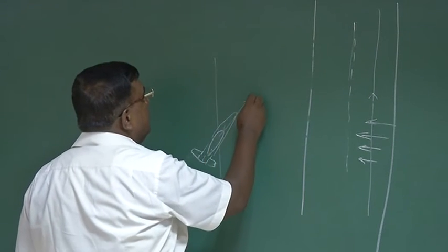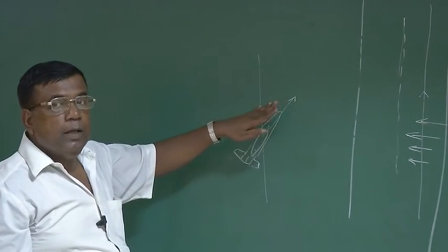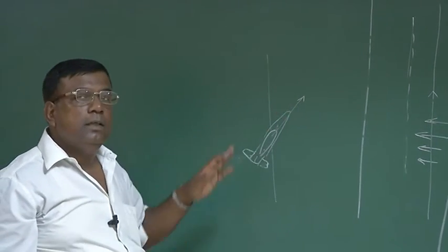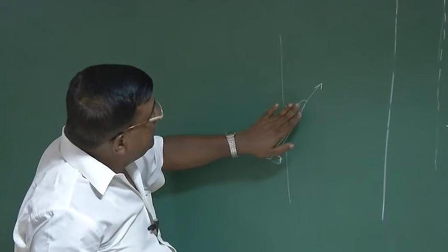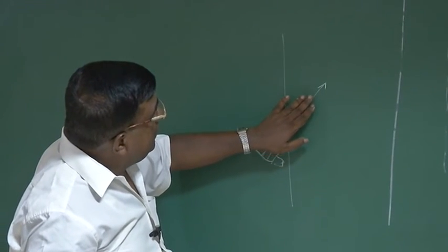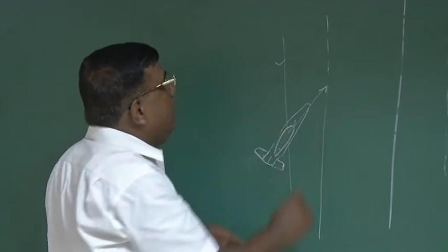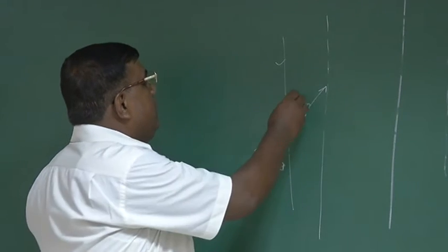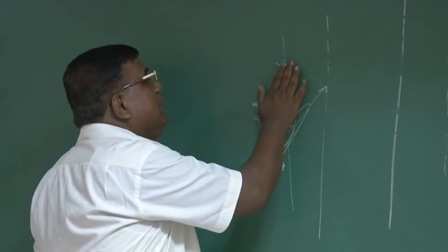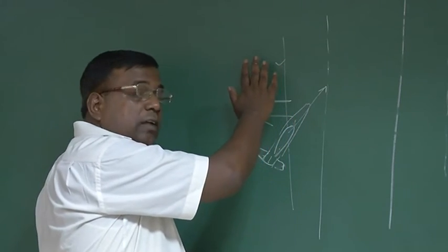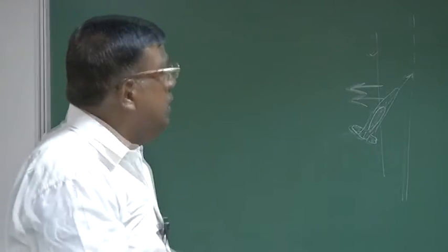I will be actually flying like this. I will try to go into the wind and ensure that through the thrust, whatever force I am getting here gets neutralized. But since I am just aiming at some other point here, which is not this point, because of this wind, I will be constantly drifted towards this direction. So at some point when I come here, I have to turn the airplane nose left, flare up and land. This is one way.